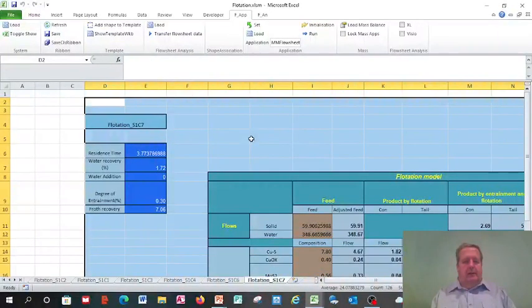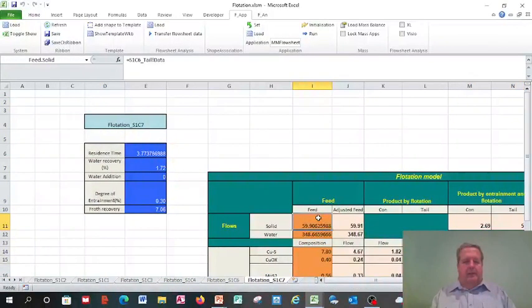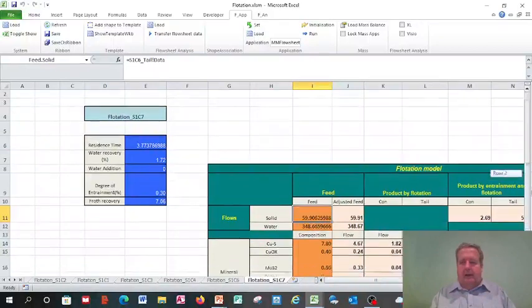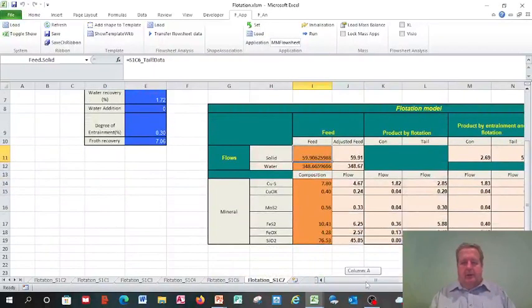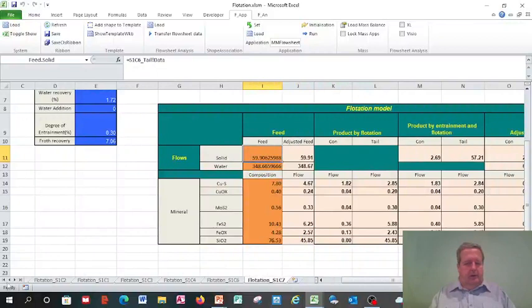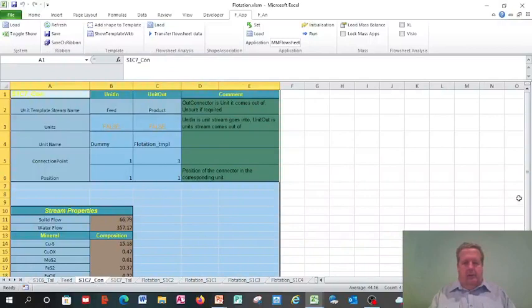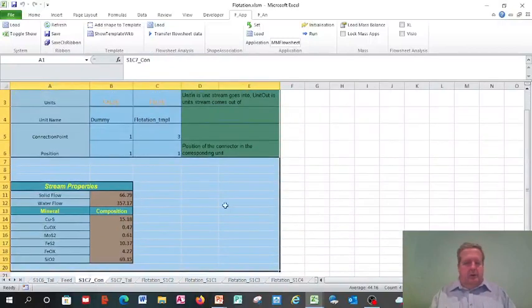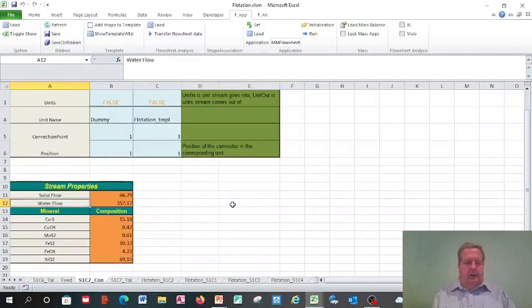And what it's done is do a replace of all those connected informations. And so by doing that, it's done all the calculations, and we can have a look at the con. We'll just go to say 7 con. This tells me the value of the con in the 7th cell. Similarly, each of the flotation models have been created. So it uses very simple concepts to simulate what otherwise would be a fairly complex system.